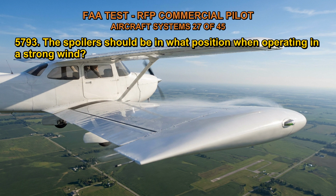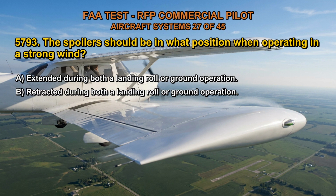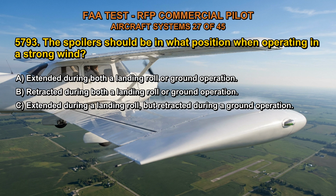5793. The spoilers should be in what position when operating in a strong wind? A. Extended during both a landing roll or ground operation. B. Retracted during both a landing roll or ground operation. C. Extended during a landing roll, but retracted during a ground operation. The correct answer is A.